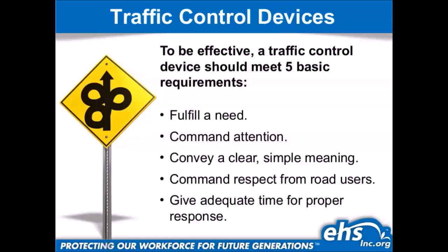So what that last bullet point means is you've got to place them in a way that you're giving them time to read them, understand them, and react to them. If you're placing them just before the work site, like 100 feet out may not be effective. Depending on the speed, the minimum you should have them out is 100. And again, these aren't things that I'm saying, it's things that the CAMUTCD says. And those are for speeds 25 or less, guys.